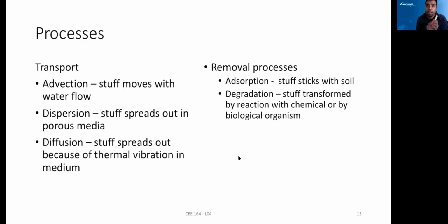So why is it important? That makes the pollutant diluted and spread around from the locations. And if the pollutant disperses around, the plume disperses, then you have to have multiple sites for treatment. So that's why it's important to know how much it disperses. And also dispersion is important because it dilutes the pollutants. That means the concentration will decrease just because it is diluted.